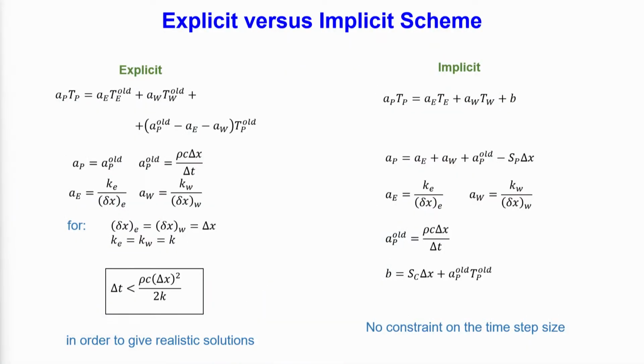So, in that way the left hand side is written in terms of the right hand side. The first two talk about the space neighbors, and the last one the time neighbor, but the space neighbors are also described on the basis of the old temperature value, because the explicit scheme says that everything is the temperature at the beginning of the time step.